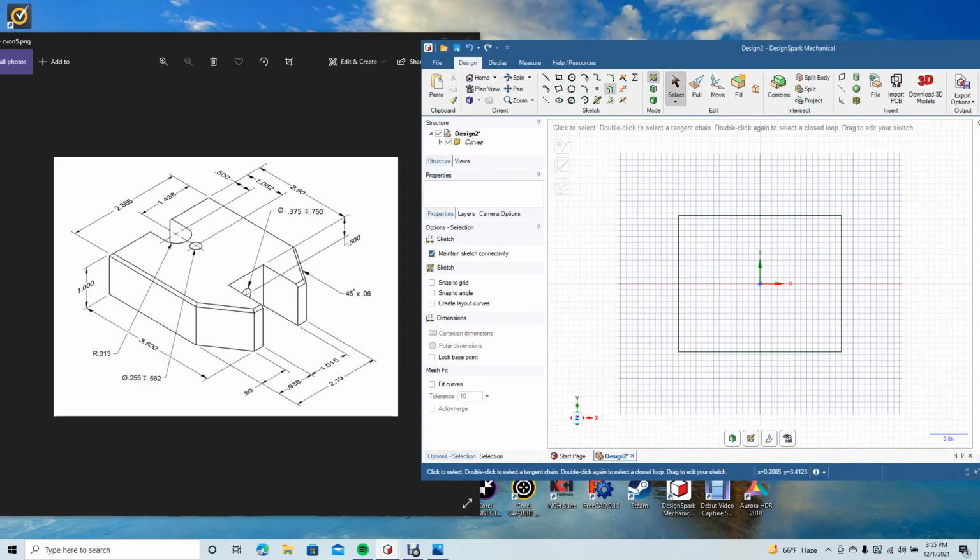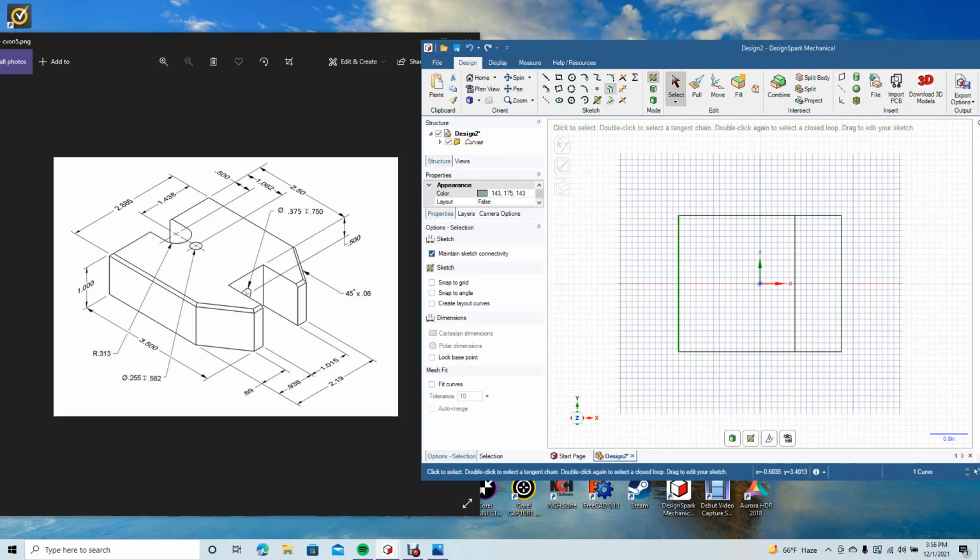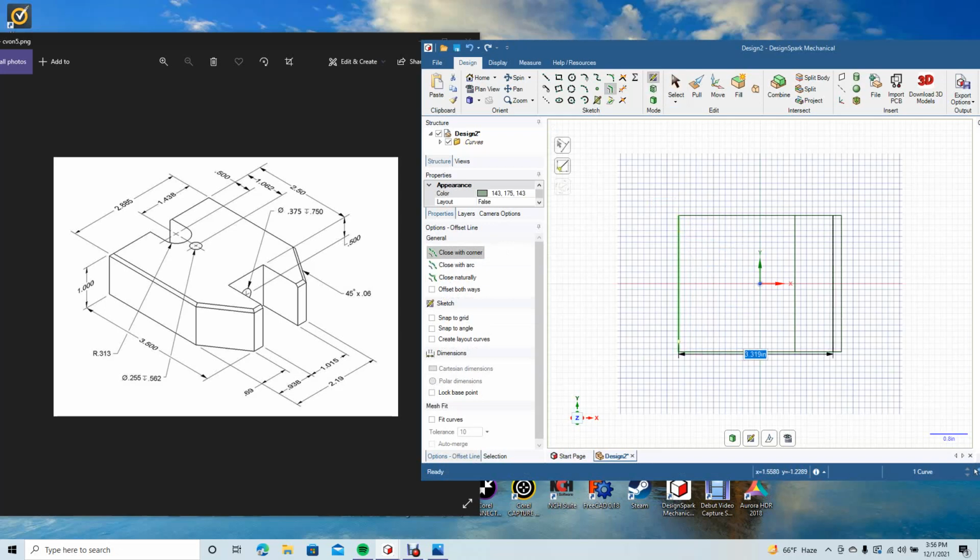Now we're going to use our offset curve. We're going to come over to the right, 2.5. Okay, now we're going to use our offset tool again. Actually, click undo that. Make sure you're not selected on any lines that you don't want to offset. So go ahead and offset. Click that line there, drag up 0.69. Go ahead and click that one on the top, drag down 0.69.